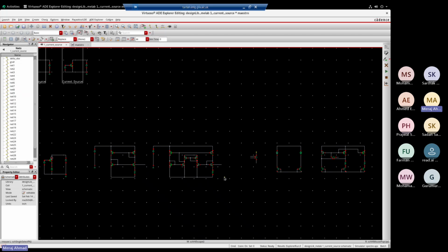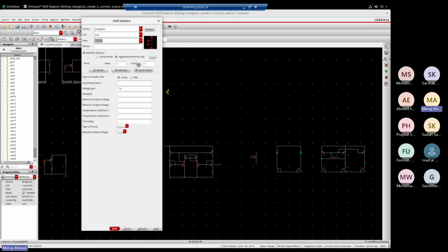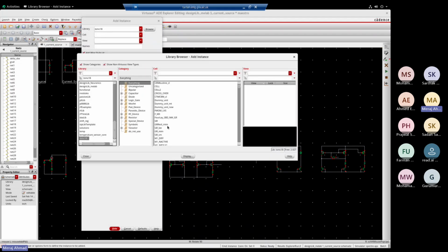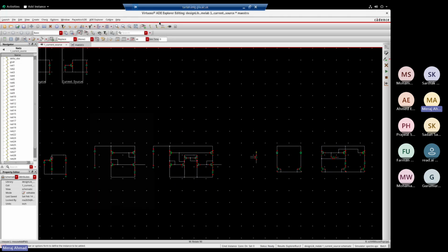If I want to, I can show you quickly what technology offers. So this is TSMC 65. You have diode, MOSFET, resistors. You have a lot of two-terminal resistors, three-terminal. These are metal resistors. You don't use this because it takes a lot of area. These two you can use. In any technology, you will have resistor and capacitor. Okay, this is how we generate a current.